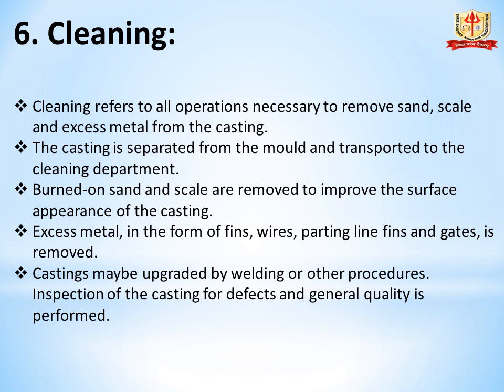Sixth step is cleaning. First point, cleaning refers to all operations necessary to remove sand, scale and excess metal from the casting. Second point, the casting is separated from the mold and transferred to the cleaning department.